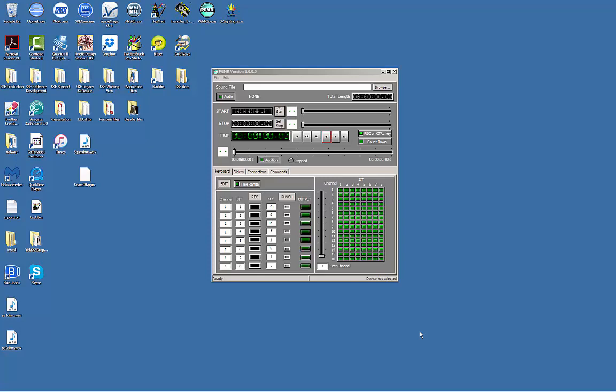RPod. Some of the features include this program works with our Minisam devices and the RPod units. The program is Ethernet bus based. It uses a custom protocol called SKE. It's a UDP type protocol that also incorporates FTP, and it allows you to connect to multiple units simultaneously. This protocol includes automatic device detection of units on your Ethernet system, and that will allow you to go out and pull them and select them as you see fit.